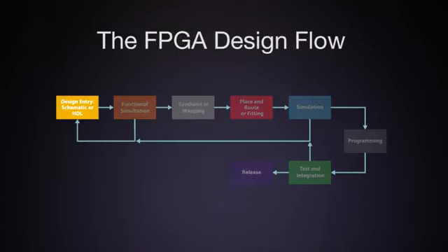The design begins with the design entry, continues with simulation to verify the logic is implemented as expected, and then the tool will perform synthesis, also called mapping, to map the logic to the device architecture. Next, the tool will create the interconnection between cells by placing and routing, or fitting, of the design.